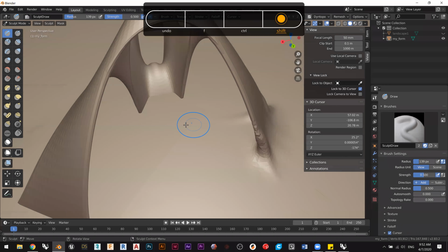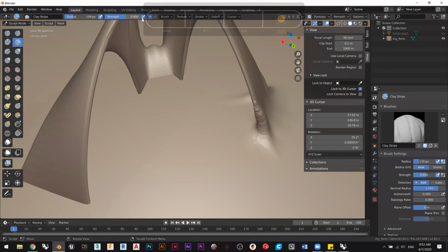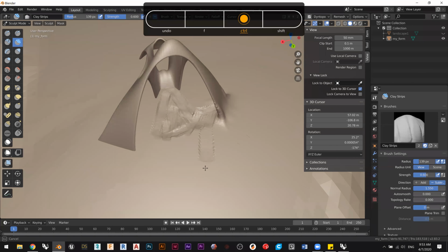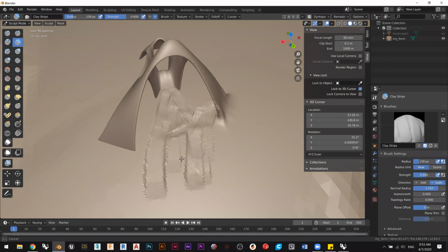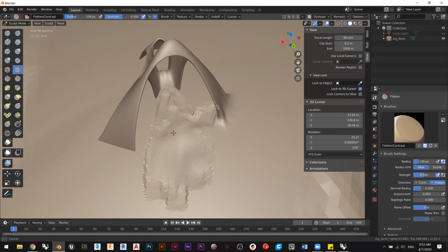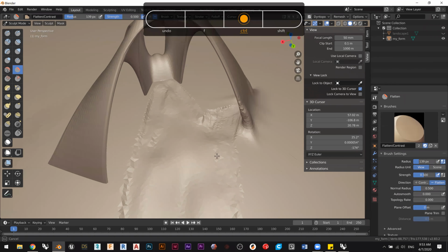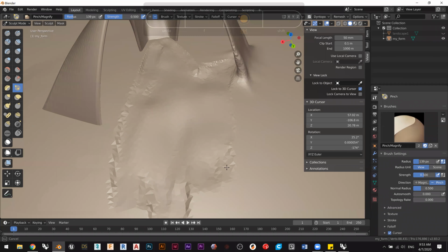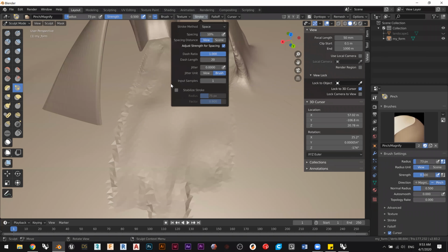So that's that. And then all you need to do is just mess around with it and see how you would treat this whole shape, right? What kind of surface quality you would give for the landscape, what kind of surface quality you would give for the shape, and that's going to be exactly the same process as I've shown you yesterday. Hitting it with flatten, hitting it with some brushes, carving in, carving out, simplifying, smoothing, and then later on creating those sweet seams with, where is it? Stabilized stroke.